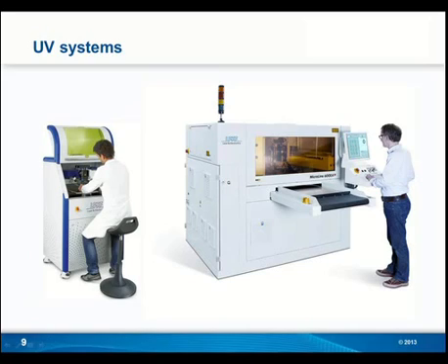Also, keep in mind we have the stronger laser source as well. That's about double the power. So that's why we need more specific information about your question. There are a lot of things that are adjustable: travel speed, pulse frequency, and the lasers also allow you to adjust power. With that, the software has a percentage and gives you an actual power output at the material, and it also knows the power output at the source. That way we can maintain machines very consistently for several years so that you can continue production applications.